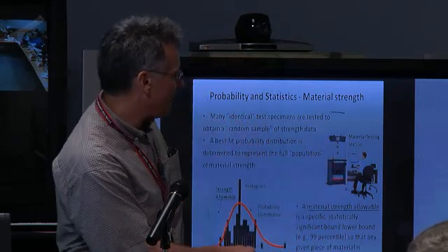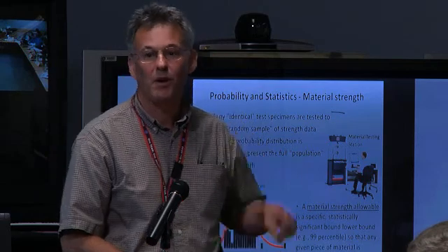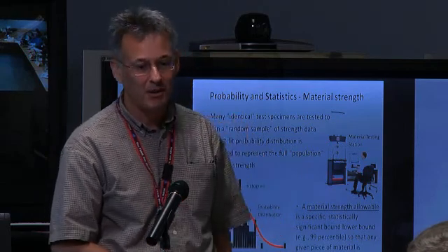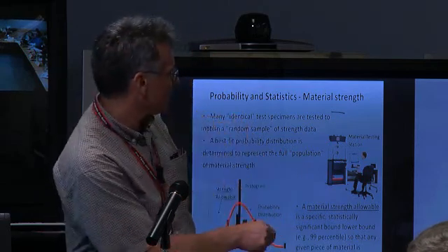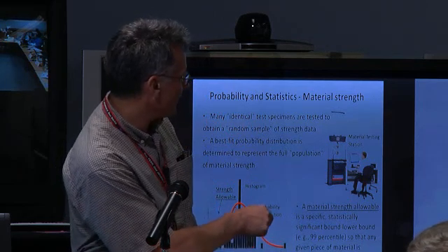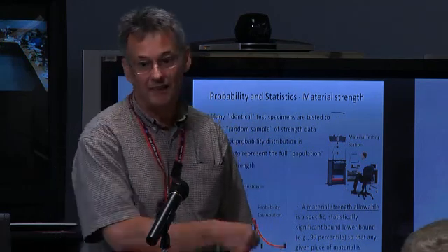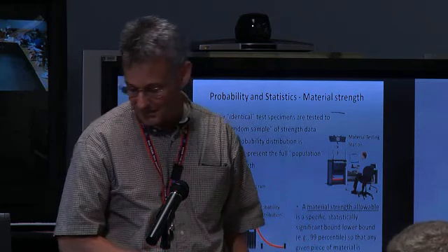You know, not only a 1 in 100 chance of failing on you, but this is the kind of data you need to have in order to do your design. It's only one piece of the problem, but it's an important piece. So basically, this material strength becomes an allowable, and what we end up doing now is taking an allowable that's some statistically significant lower bound of all that data, and we'll run that data.